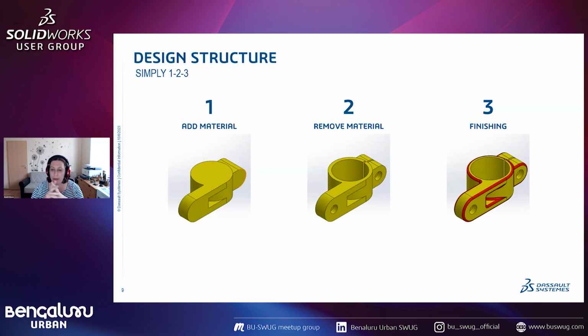Yeah, that's a really good question, and I will answer in 2 different ways. One is the one I'm showing here with the simple model and the finishing fillets, but sometimes you have fillets which are for machining. When we have a machined part and we have a cavity inside, we must have a fillet on every corner.